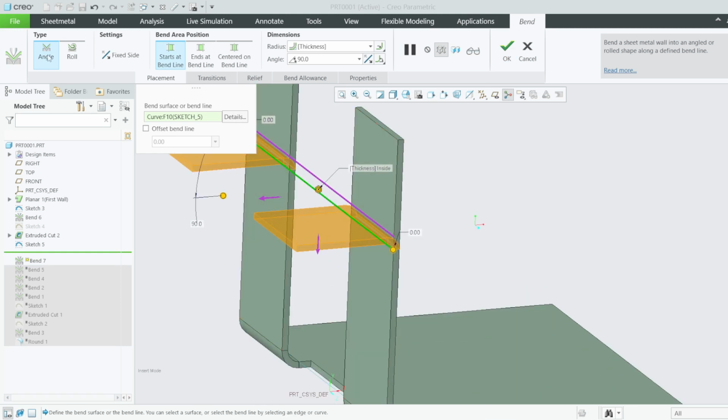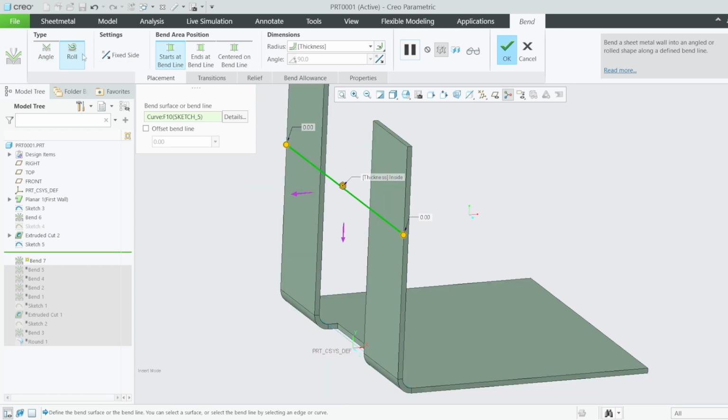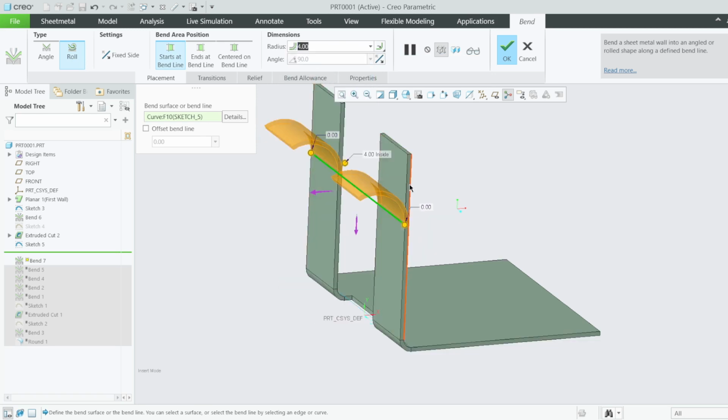Instead of using algo, use a roll, okay? Because they are made by rolling the flat surface until it takes that shape using a die. Therefore, for you to roll, you just control the roll using radius. You can see after selecting the roll, nothing is formed, nothing is created, because for this to happen, you need a minimum bed thickness. Therefore, if you now change this value to 1, nothing happens. To 4, starts to roll.